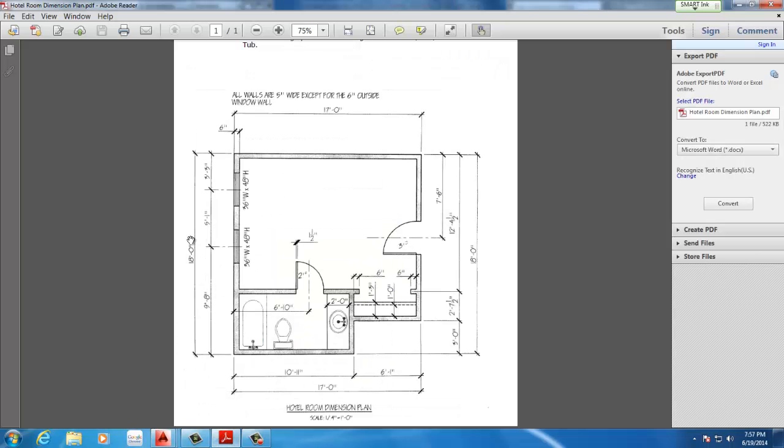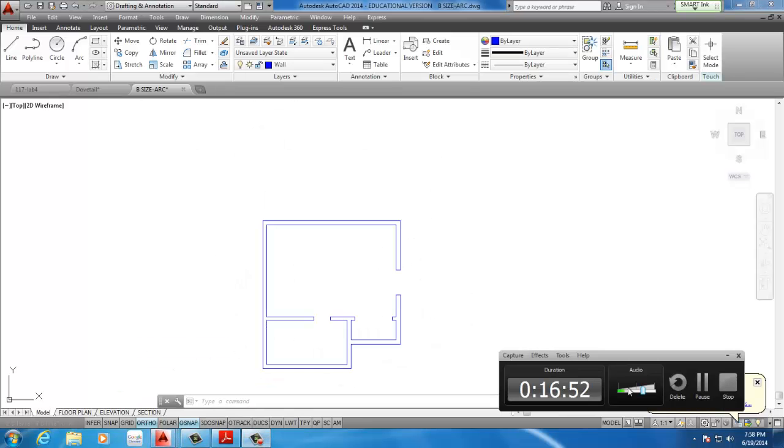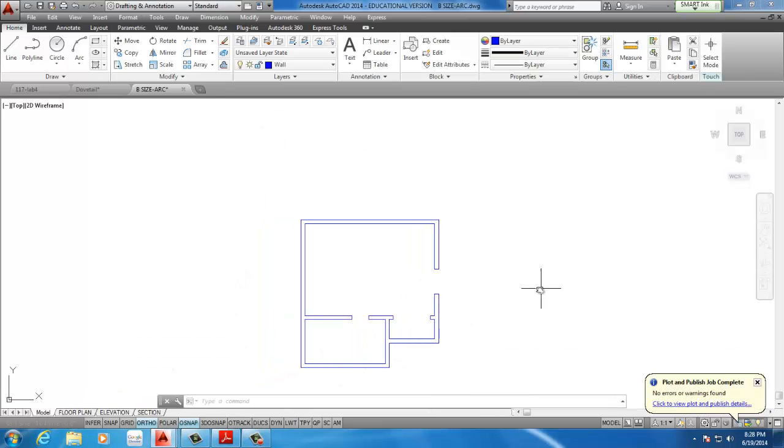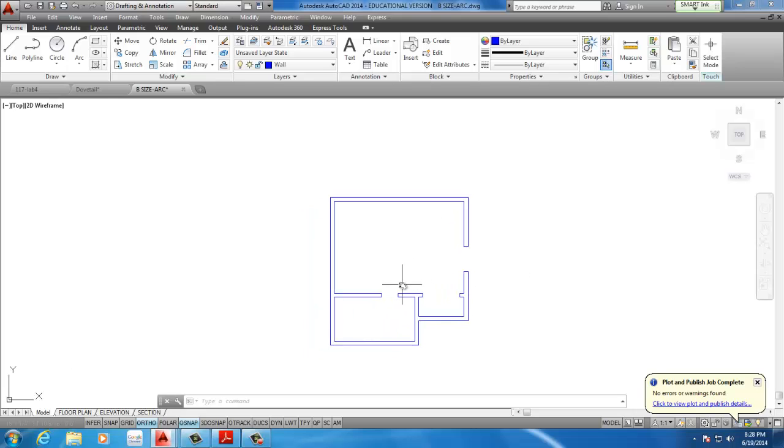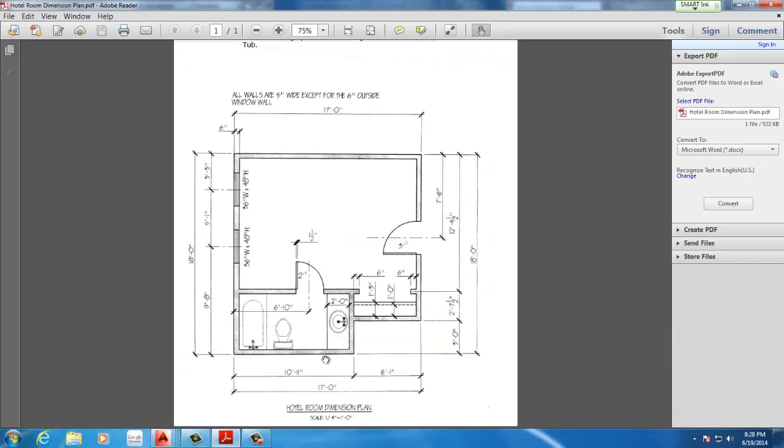So if you see on your drawings, the windows are shown on the left side, like so. Alright, so we're going to put in the windows. To do that, I'm going to use the offset command this time. I'm going to offset this exterior line. Or I can start from this line, the exterior, 3 feet and 3 inches to get to the center of the window,